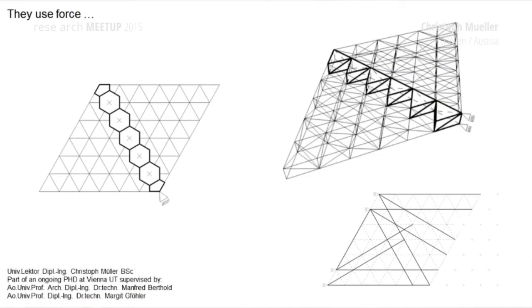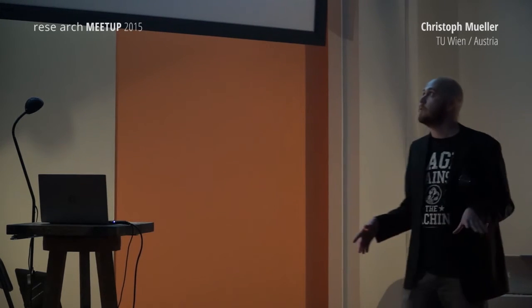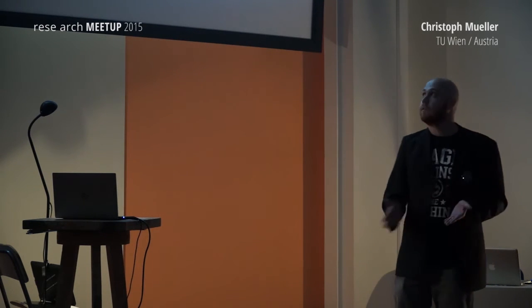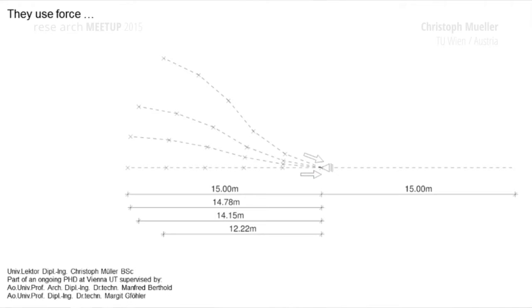So coming to the idea of load deflection, the first step was, and I guess you have to do it to prove somehow an overall structural performance of the system. The first step was taking sections and asking the question where would be the worst case of the whole structure. And of course, you can see that these diagonals, these are the worst cases you could have.